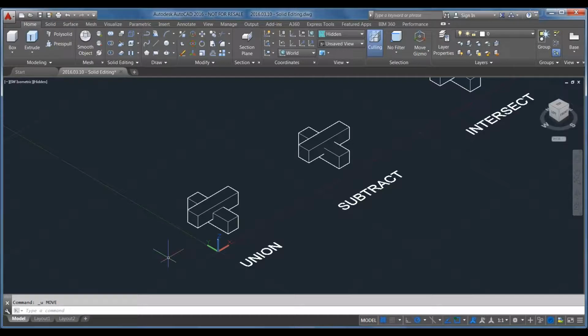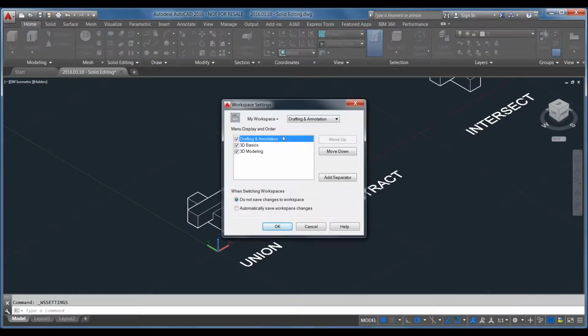Well, okay, so in AutoCAD Architecture, there is just the architecture workspace that you start with. It's the default. But you can switch to the basic AutoCAD profile. If you switch over to that profile, all of these workspaces are available: Drafting and Annotation, 3D Basics, and 3D Modeling.